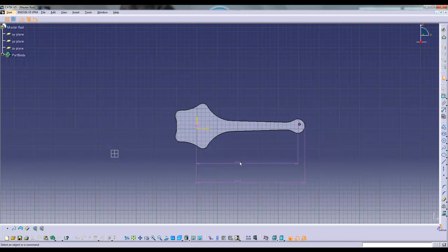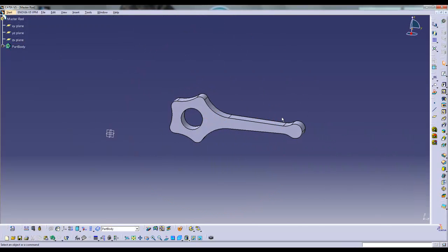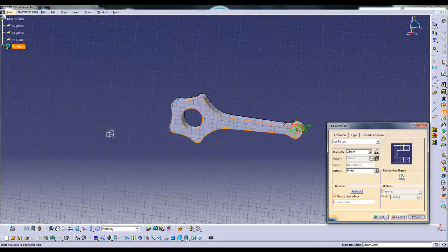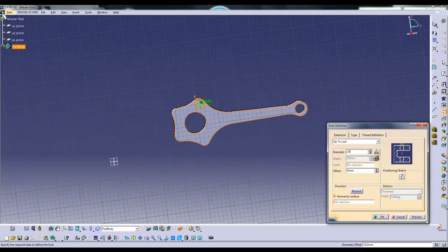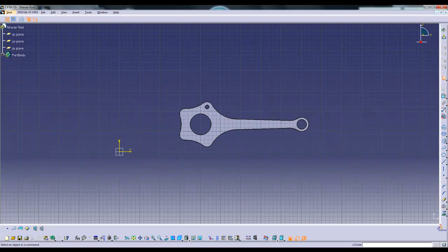Directly constrain the point to the object as shown. The step you have seen is to ensure that there are no conflicts. Reference points in sketches will often lead to complications. Selecting the appropriate surface and a corresponding arc, and using the hole command will center the hole appropriately. Simply choose the appropriate dimension for the hole.